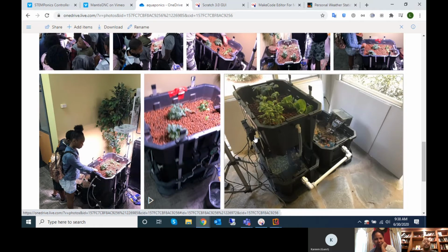In aquaponics, there's a method called ebb and flow. That's where you cycle your water, you hold it for a while to let the roots absorb the nutrients, and then you drain it, right? Inside of this system, the fish are urinating, they're creating ammonia, and that ammonia goes through this biological cycle where the bacteria and the ammonia kind of do some magic, and they create nitrites, and then nitrates, which the plants love.